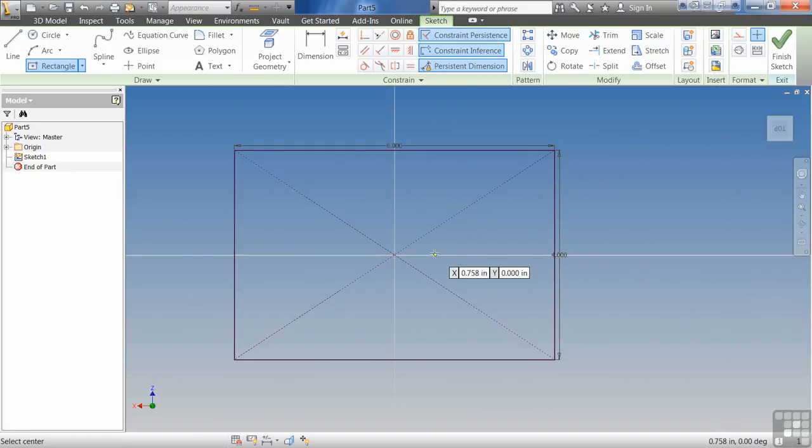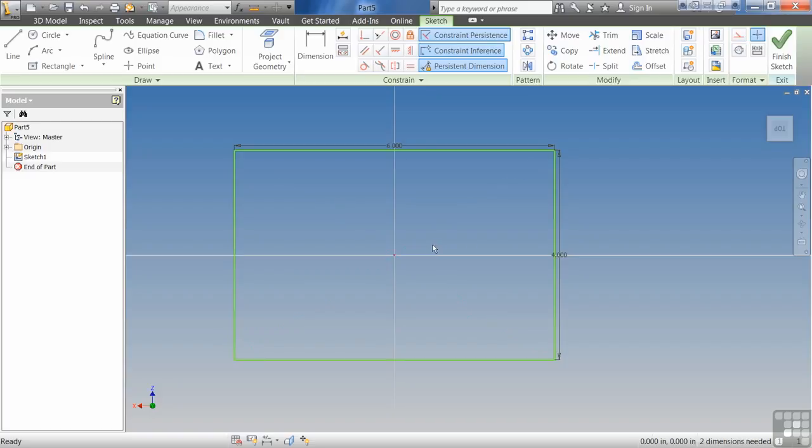The reason I chose a center point rectangle is you'll notice there's already 2 construction lines created to create the center location. Just like constraints and dimensions and everything else Inventor will automatically do for you, just like the automatically created constraints, Inventor sometimes will automatically create construction geometry. And just like those constraints, we can delete those and create our own.